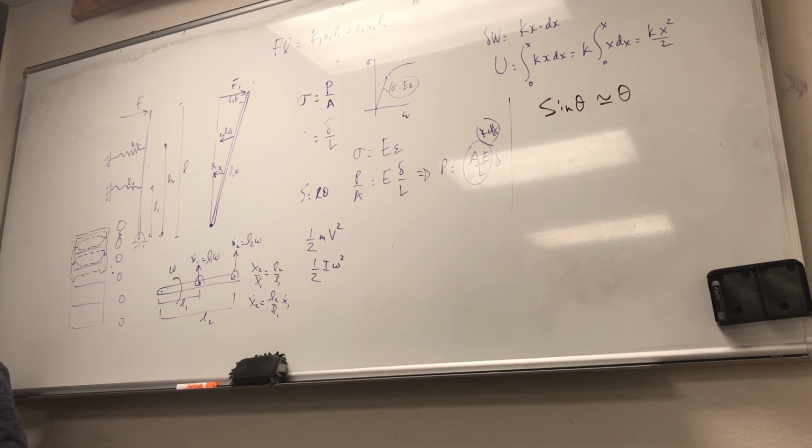So here, what do you have? You have the rack traveling with linear velocity, but the pinion is rotating with a rotational velocity, which is theta dot, okay? So what is my equivalent? In other words, you're taking these two masses and you want to make an equivalent one. So the criteria then is that the kinetic energy is equal to the sum of the translational plus the rotational, right? And then the equivalent kinetic energy is simply 1/2 of m equivalent times x dot equivalent squared.